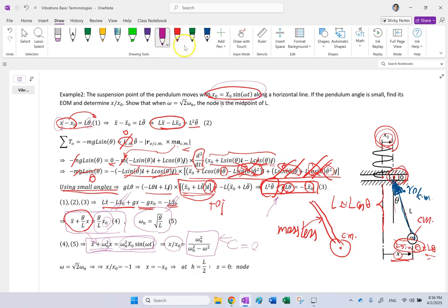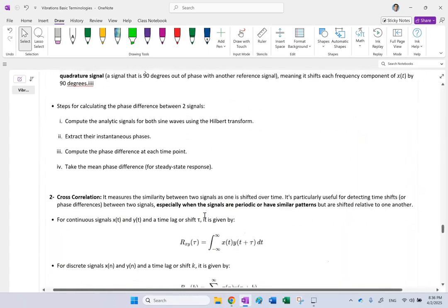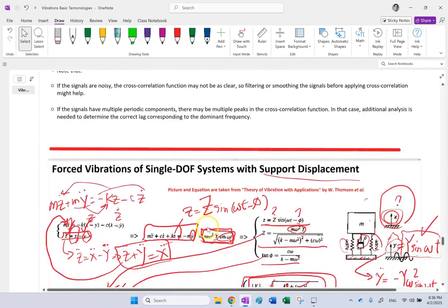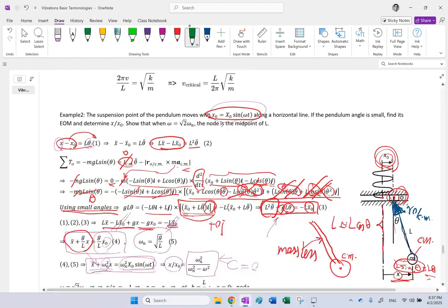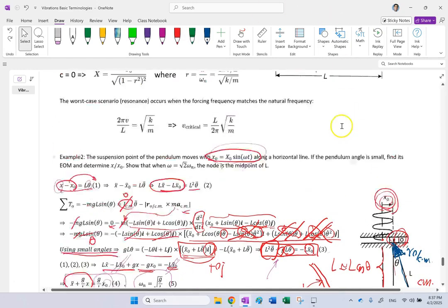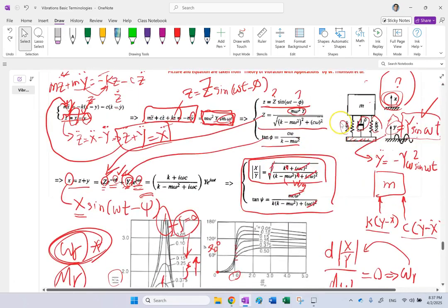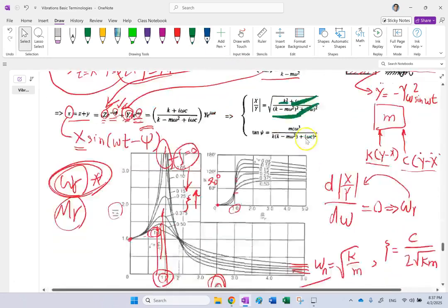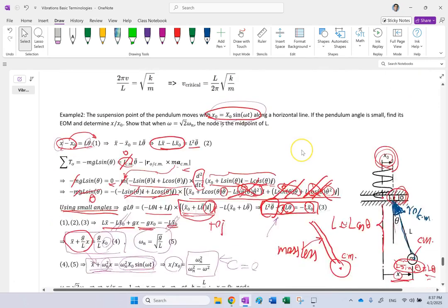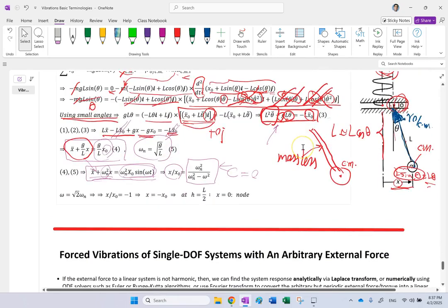So if I want to get any of those formulas that I learned in the past, all I need to do is to get rid of C. Remember, in this one here, I can use any of them, but I have to get rid of C. And if you simplify this, if you remember, it was basically omega n squared over omega n squared minus omega squared.